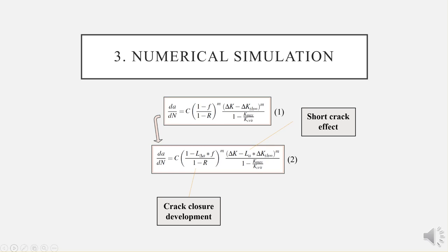For this reason, we multiplied Newman's F parameter by a function that goes from 0 to 1 as the crack evolves from its original state. The variable controlling this crack closure buildup is the distance traveled by the crack front, measured from the initial state. The approximate distance required to build up this effect was assumed to be in the order of the El-Haddad parameter. This assumption obviously requires further research, which will be done in the near future, in order to determine the exact distance required for the crack to reach a steady state situation.